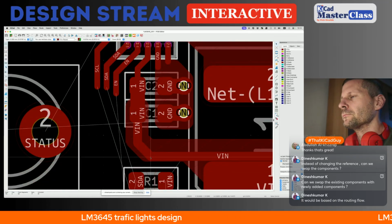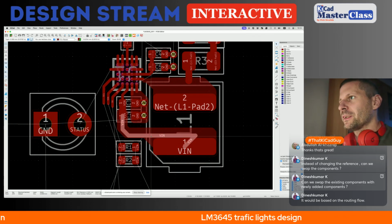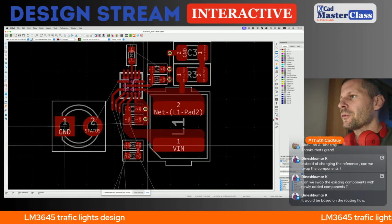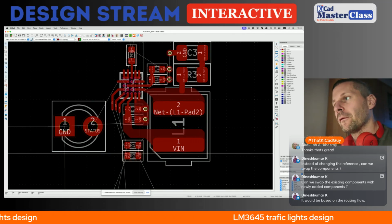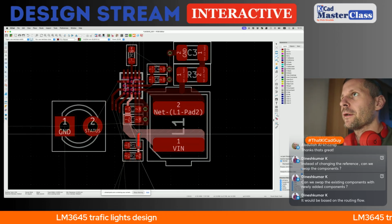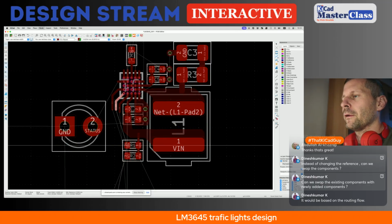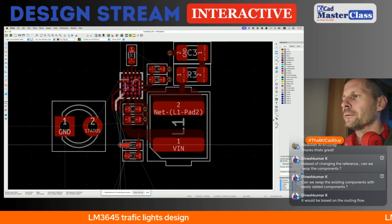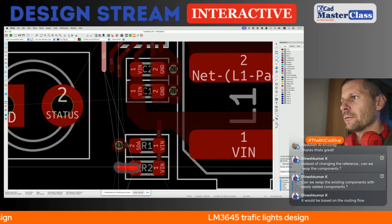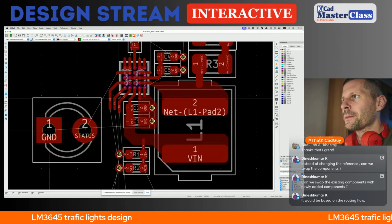Okay, it looks good. We can remove the auxiliary track, but not the entire track. I will place a thinner track here, because I want easier soldering to avoid the tombstone effect.